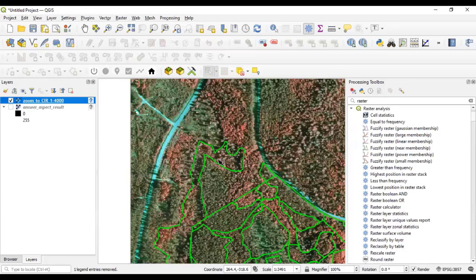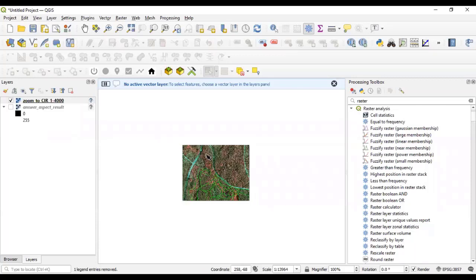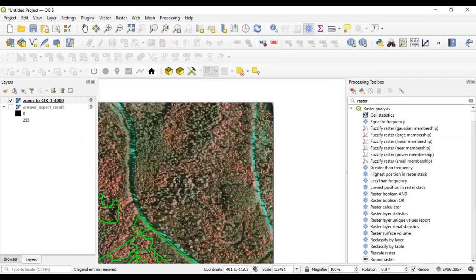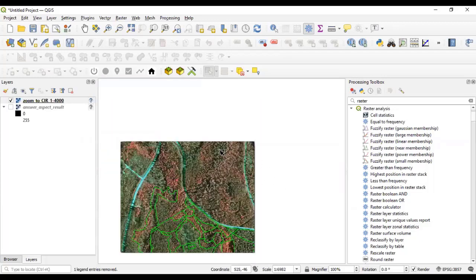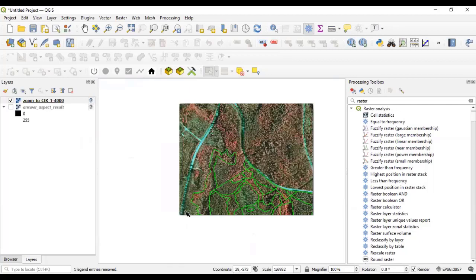Possibly, if it is georeference, you can go ahead and digitize, possibly bring out the road. Now, that is to say you are converting or polygonizing. If you remember from the beginning of this course, we talked about data conversion, where you can convert raster data to a shapefile data, okay? Which is now, if I want to convert, I create a line and then digitize this road. If I have this road in my vector now, I've already converted the information in this raster data to a vector data. Okay, that is polygonization in GIS.